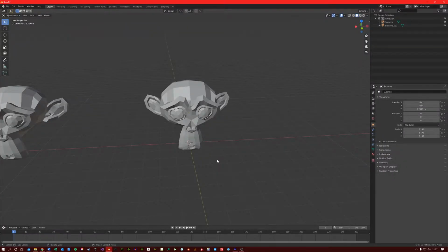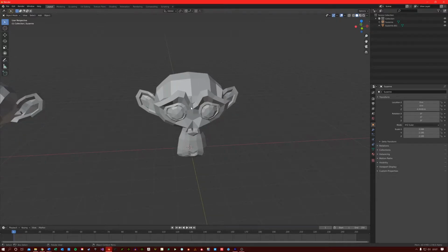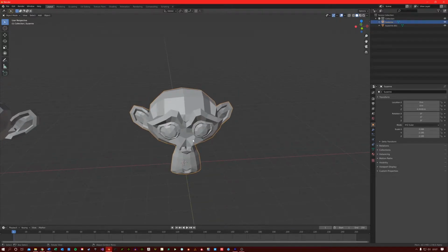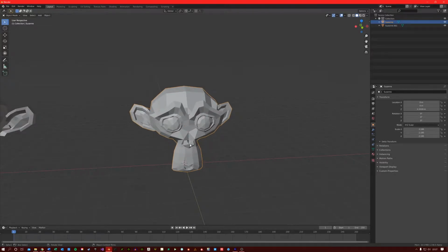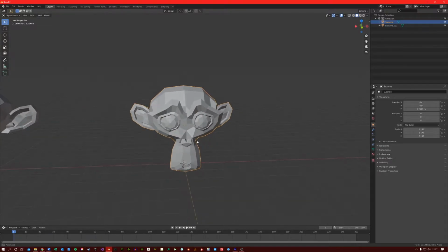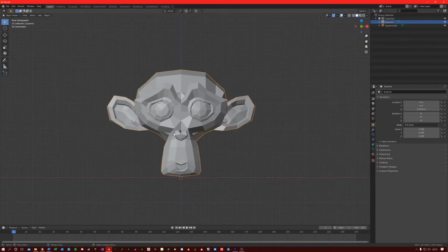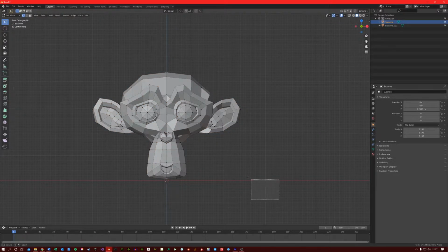In this video, we are going to go over some more useful tips and tricks to help you with your Blender experience. The first thing I want to show you is an easy way to make a clean selection of your mesh's vertices. If I go into orthographic mode and then pick a particular perspective, like if we click 1 on the number pad, it will take us into the front perspective. And I'll come into edit mode, and I'll make sure I'm in face select mode actually.